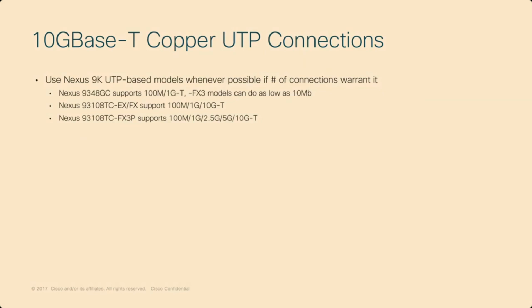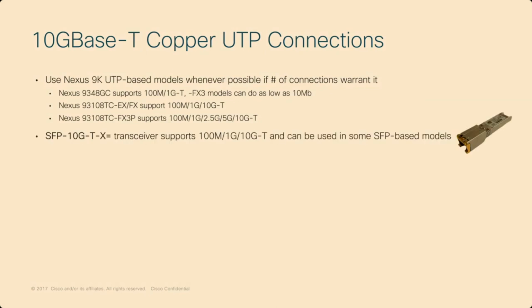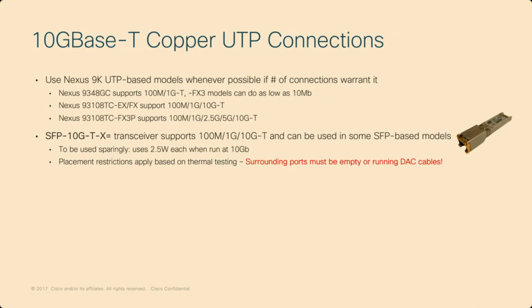But let's say, for example, I have only a handful of devices there, and it's not worth buying a separate switch just to handle those connections. Well, we do actually offer a transceiver that can be used for 10G base T, and customers have been asking for this for a while. But the downside is that they take a lot of heat and a lot of power. Unfortunately, because each one uses about 2.5 watts, you have some placement restrictions.